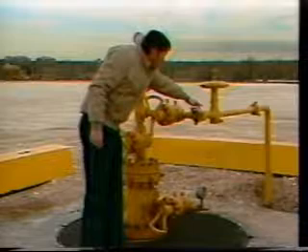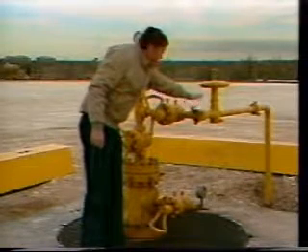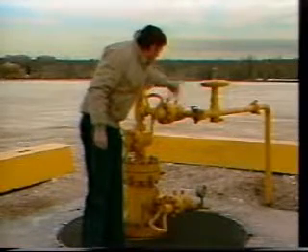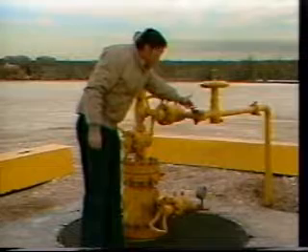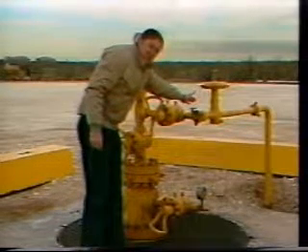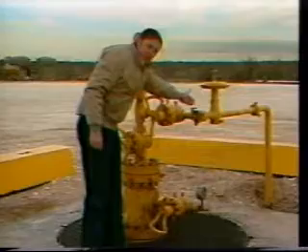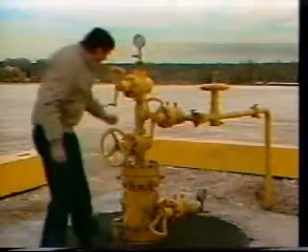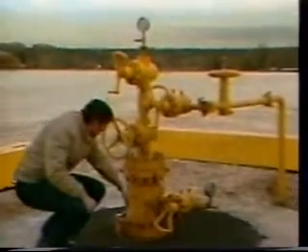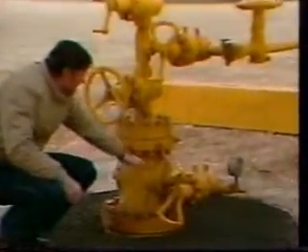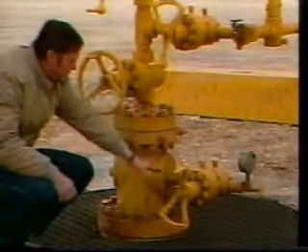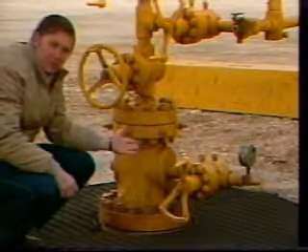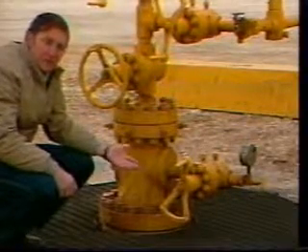This orifice and its insert can be changed to control the rate at which the well produces. The operator will merely close the valves, unlatch this right here, and change the insert size so as to control the flow rate. Larger opening, higher production rate; smaller opening, lower production rate. The pressure between the annulus and the tubing is measured here on this gauge by opening this valve to allow the pressure to be read. There are some other wells producing on this lease using beam pumping.